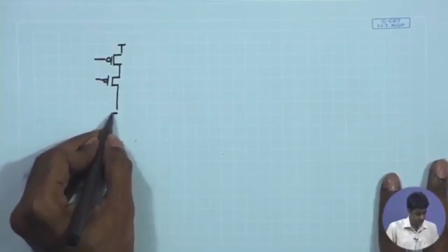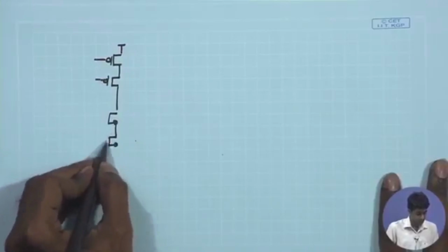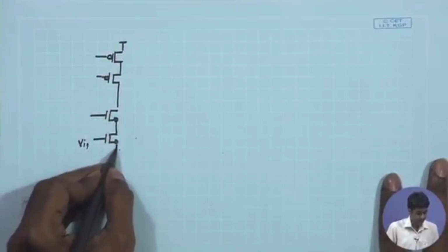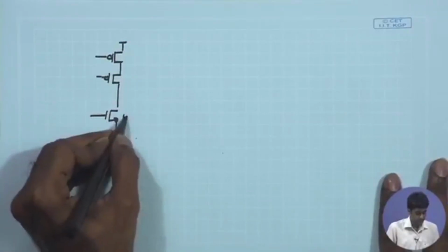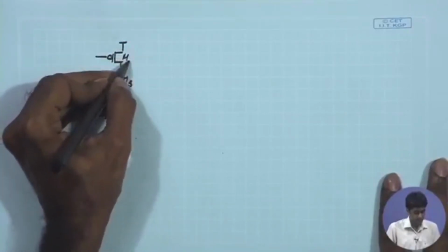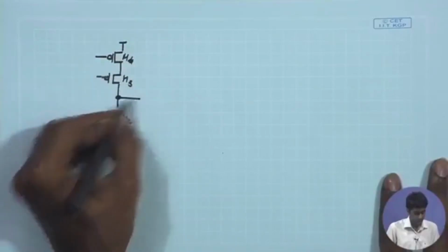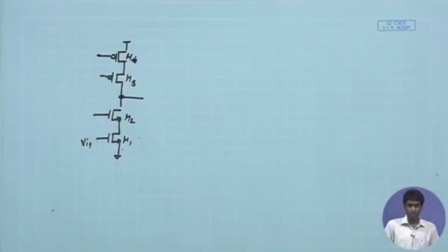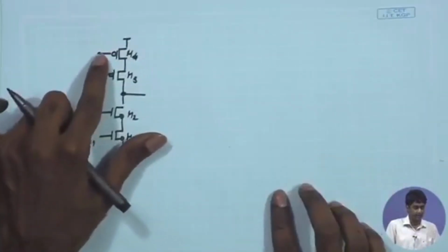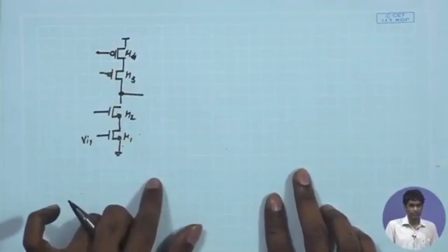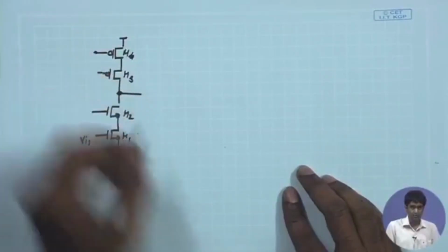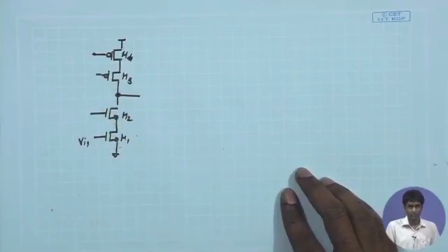So we have looked into single stage, single ended cascode amplifier where the input signal is applied at the gate of M1 and the output is taken at the drain of M3 and M2. You have some appropriate bias point over here. We also saw one easy way of biasing the gate of M4 and M3 so that you can get an appropriate signal swing over here. And we also analyzed the output signal swing, what is the maximum and minimum output signal swing.